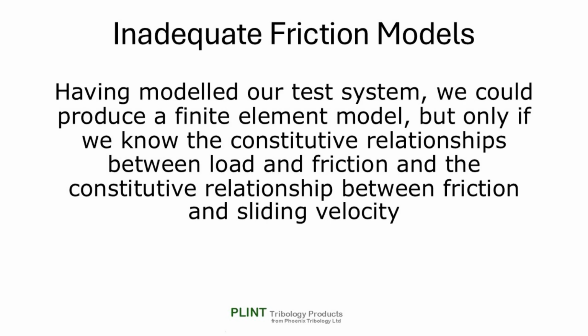It will be apparent that tribo contacts in general, even with significant stiffness in the friction plane, are likely to be subject to small amplitude vibrations. These may not only affect the frictional response, but may also affect the dynamic load. We know the limitations of the Amontons-Coulomb laws of friction. In view of the dynamics of our diverse test systems, how far can we progress without replacing Coulomb's law with some form of rate and state friction model?